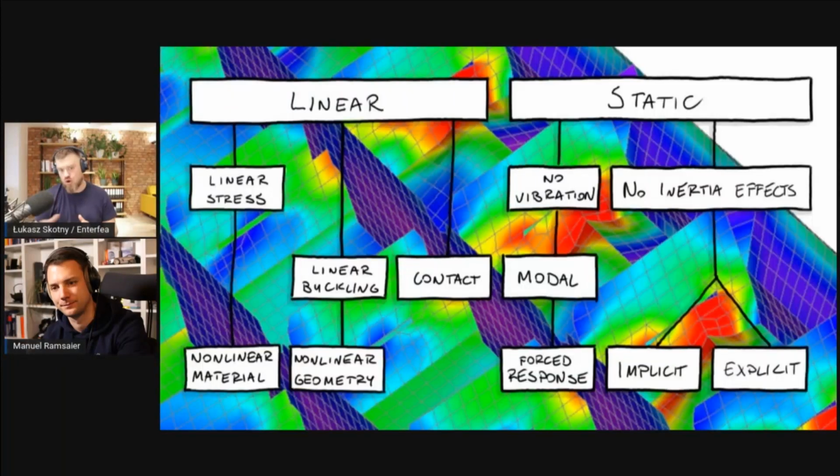But if you have a longer time, implicit solver with your time step definition is needed, because while you will waste time to converge each step, at least you will get somewhere at the end. If you converge. So that would be the difference. All right. If converge, of course. Like you can have a lot of problems along the way. Explicit, it's easier to converge, but you have to make sure that you have a very small time.